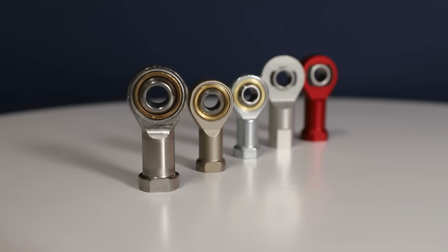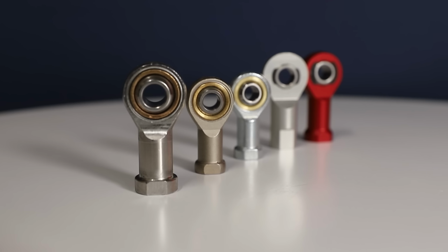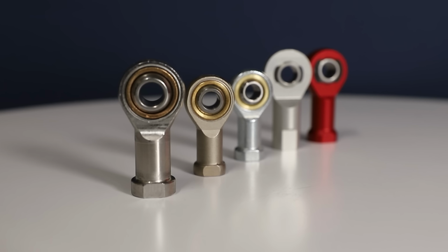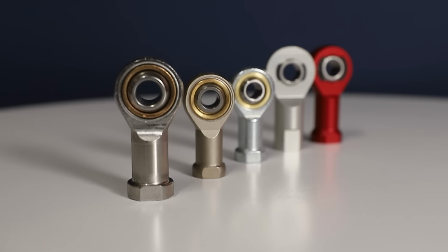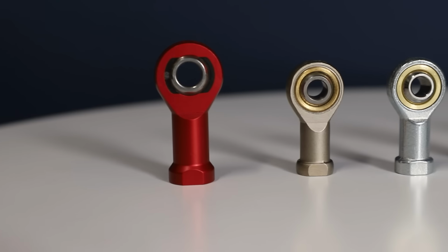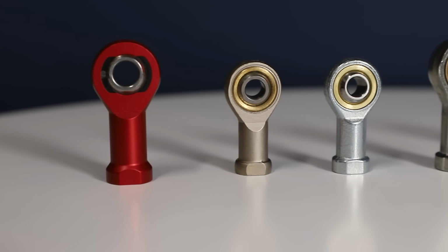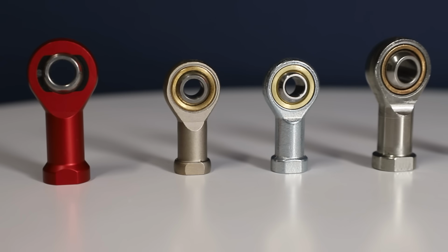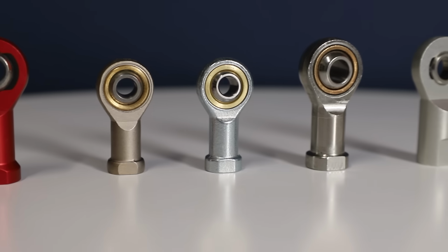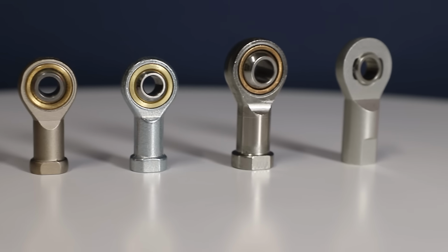In dusty or contaminated environments, rod ends that tolerate particle ingress should be selected. Either sliding type or sealed bearings work best here. When corrosion or humidity is present, or for medical or food and beverage environments, rod ends can be made of corrosion-resistant and washdown compliant materials like stainless steel.